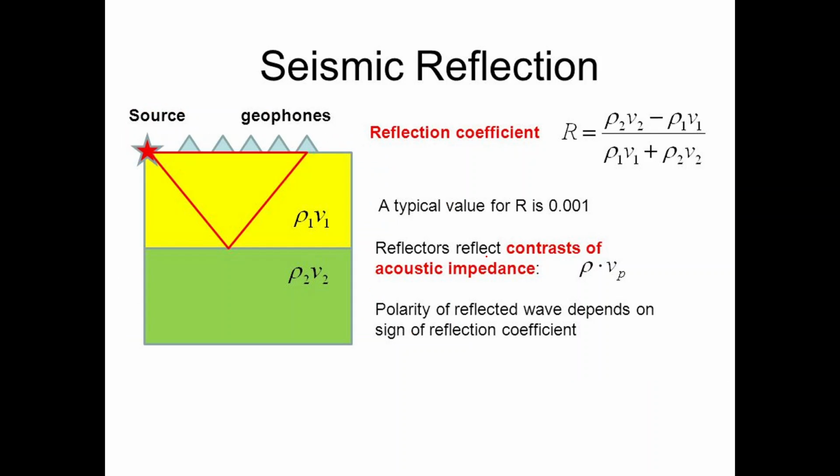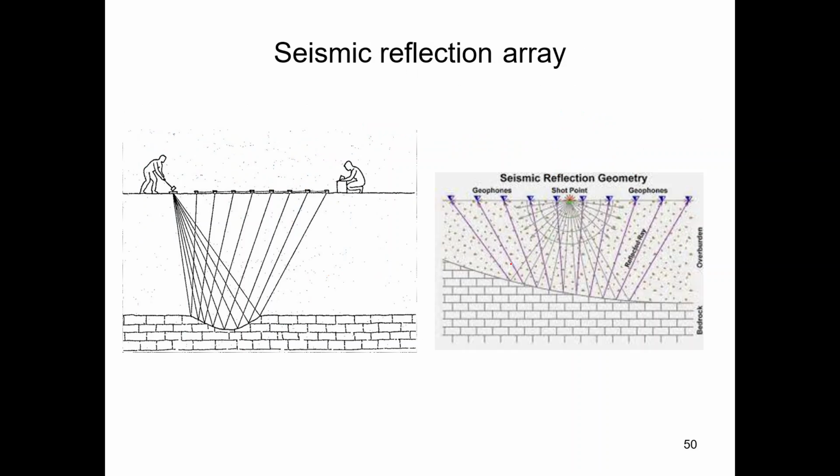This is talking about amplitude. If you have a big difference, we have a very high reflection amplitude. So the greater the contrast, the higher the amplitude. Based on this amplitude across the survey line, we can check the profile of the soil layers.